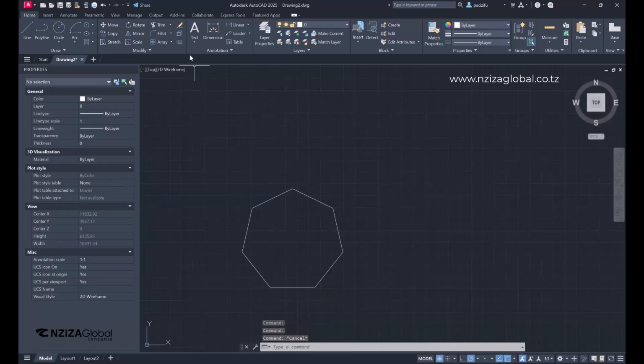So for the offset, we can click on offset so that we may have the offset of the sides. After clicking on offset, you can have some of the commands that you are going to follow. Specify the offset distance. Maybe we are using millimeter. We can have 200 as the thickness or the offset distance. Then enter. You click on your line.